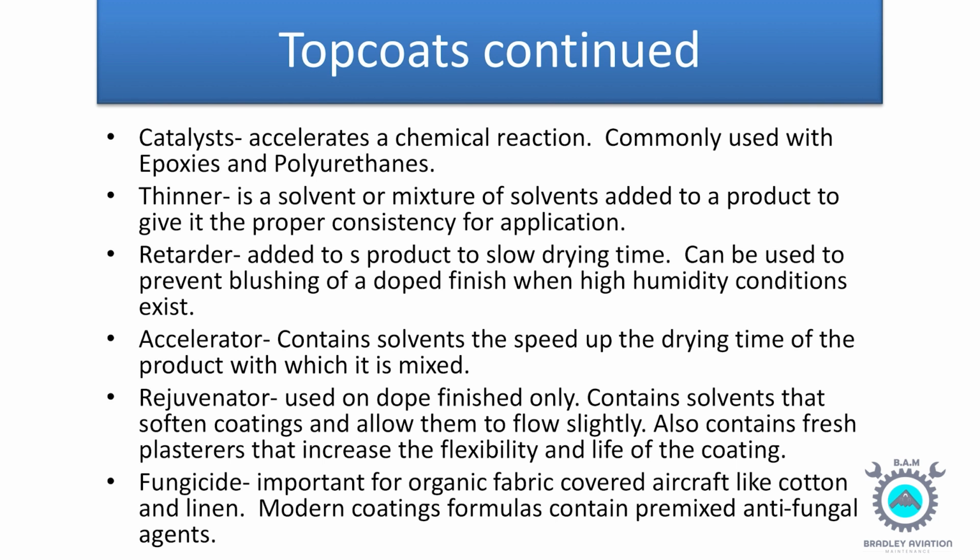Retarder, added to a product to slow drying time, can be used to prevent blushing of a doped finish when high humidity conditions exist. Accelerator contains solvents that speed up the drying time of the product with which it is mixed. Rejuvenator, used on dope finishes only, contains solvents that soften coatings and allow them to flow slightly. It also contains fresh plasticizers that increase the flexibility and life of the coating.